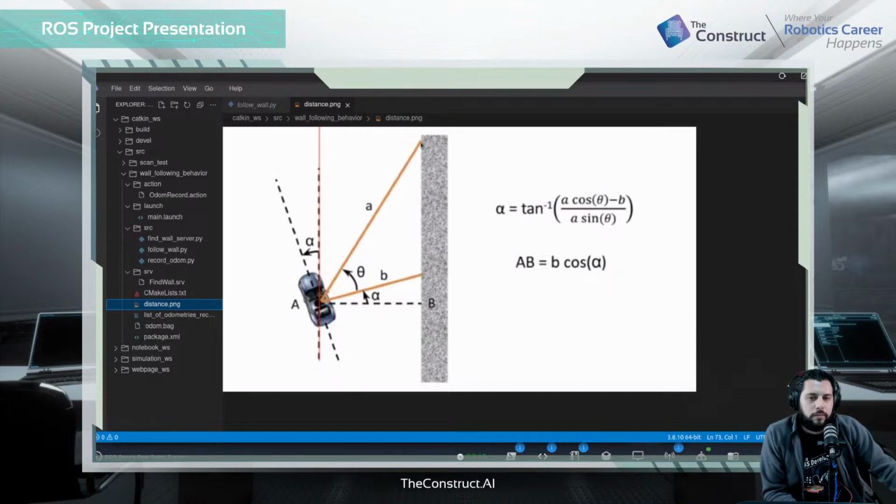So I have added a laser. I have read another laser beam from the LiDAR, which is A, and I used trigonometry. So I have now this triangle and this triangle, and by substituting the suitable angles, I can know the perpendicular distance. Also, I can know the angle alpha, which is how much my robot deviated from being straight.